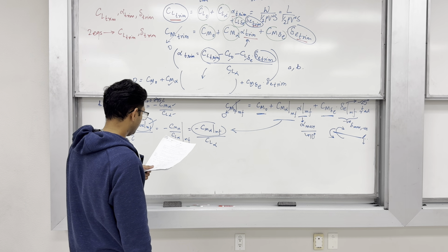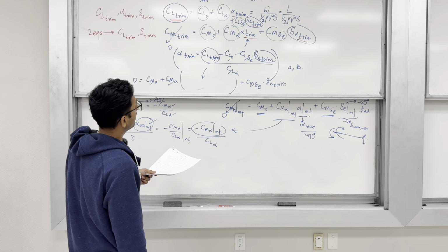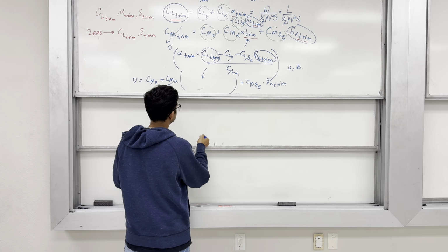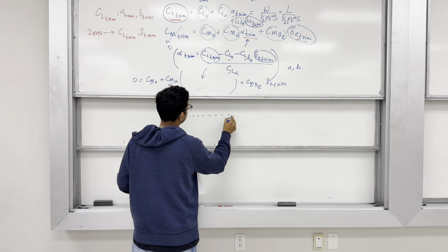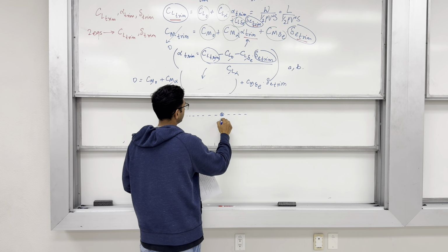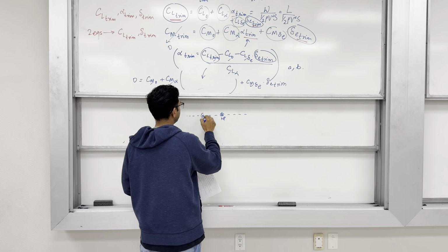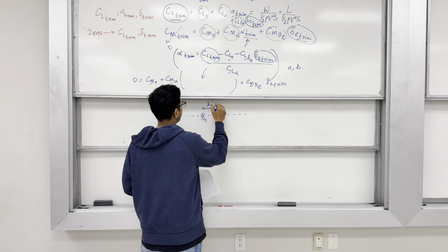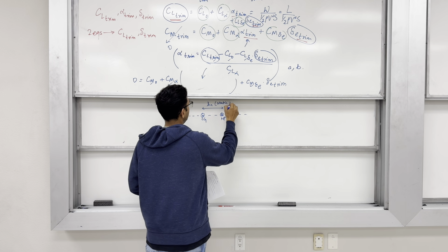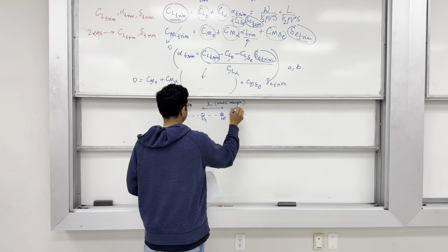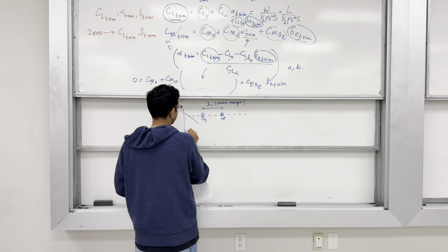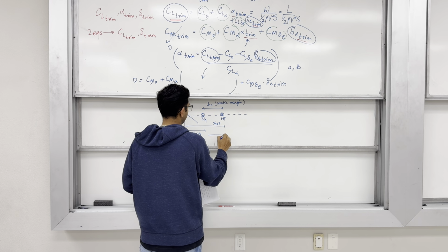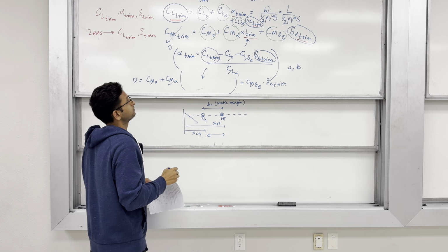Finally, illustrate the C g margin corresponding to all available information. As discussed in the previous discussion session, the first basic step is to draw the fuselage line, and mark a place for the neutral point that should be behind the place you mark for C g. It is okay if you show this to be the static margin or just write static margin, or you draw a wing and then show that this is x C g and this is x neutral point and this is static margin, that is fine too.